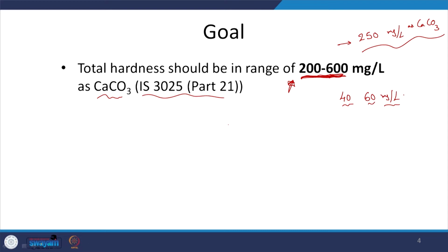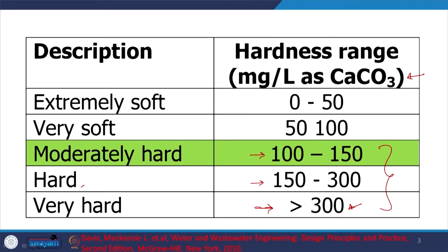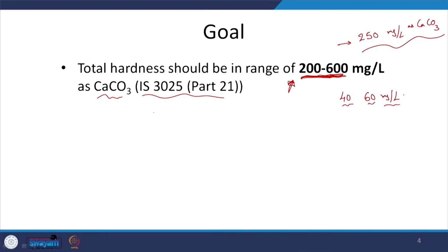In this context, we started coming across some terms, right. What is hardness, or this unit milligram per liter as CaCO3? I am assuming we might have discussed this elsewhere in this course, but nowhere is it more relevant than when we discuss hardness. Here I am talking about hardness due to calcium, hardness due to magnesium. I can't always keep talking about the concentration of calcium and magnesium when I talk to someone about the hardness of water.